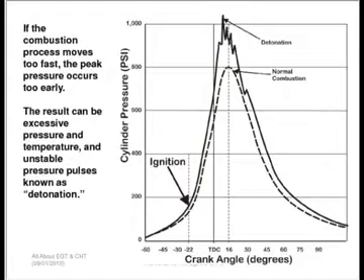And when we look at a pressure trace in a cylinder that's undergoing detonation, this is what we see. We see a high peak and all sorts of nasty-looking ringing that is making it clear that the combustion event has stopped burning smoothly and is starting to go off in little abnormal pockets like firecrackers in a sense. And that's what's known as detonation.